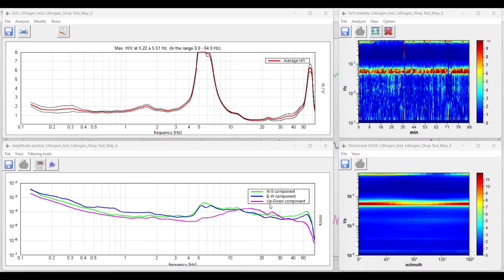One observation we can already make from those two plots is that there appear to be two major seismic interfaces or impedance contrasts in the data, one at around 5 Hz and another at around 56 Hz. At around 5 Hz, the gap between the horizontal curve and the vertical curve is the greatest, which is why we see a peak in the H/V ratio plot.